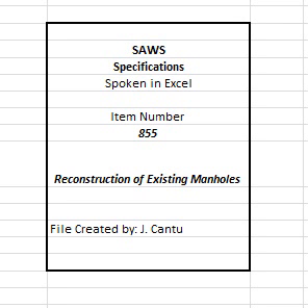See SAWS APL. A. Prior to coating, all manholes shall be hydrostatic tested and/or vacuum tested, and approved by inspector or engineer. B. For existing structures to be rehabilitated, first, apply a combination of cementitious coatings followed by an approved epoxy coating. List of current approved coatings is listed in SAWS most current APL. C. Kerneos Sperco 2000 HS and PG, applied at the required 1-inch thick application, is the only product approved which does not require a subsequent epoxy coating.